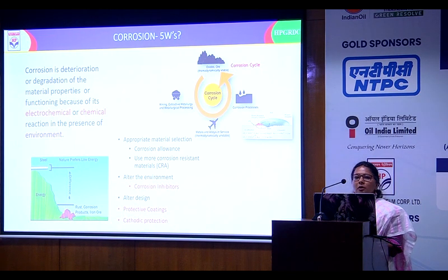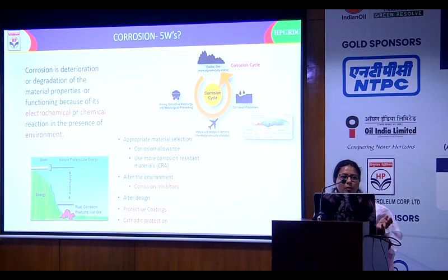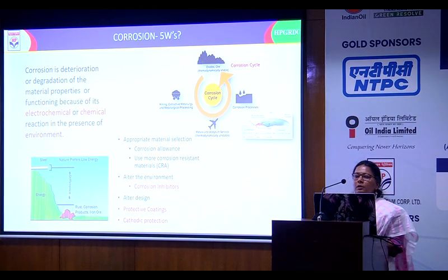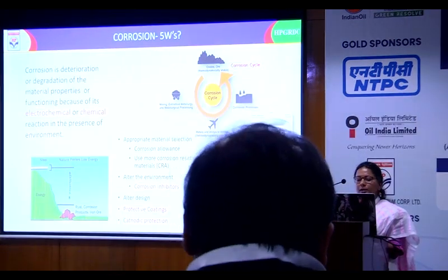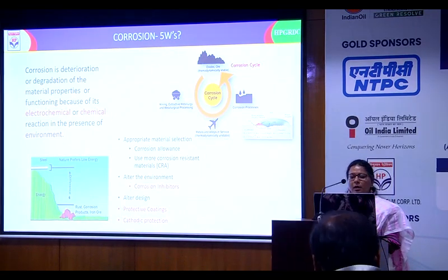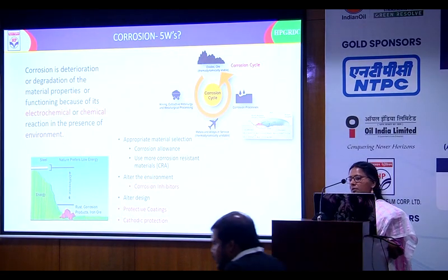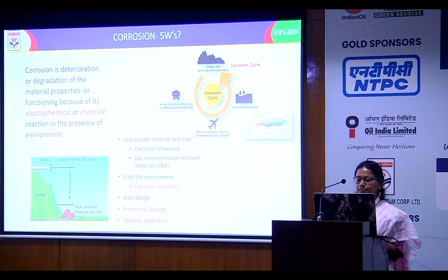And since all our assets, the refineries, even the power plants, what we heard in the morning, are maybe 50 plus years old, 5 decades now, the last two resorts are very much within our control. That is the protective coating and substance in conjunction with the cathodic protection.